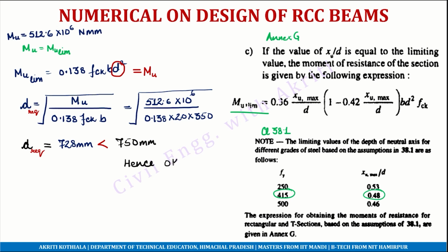Now this is important because earlier when our section failed, rather than taking the value of 704 exactly, we increased the value by 50 mm approximately so that we could satisfy this check. This is the reason, rather than taking 700 as the new value, I assumed the value to be equal to 750 mm and the overall depth to be equal to 800 mm. You can assume a higher value also if you want to avoid failure at this stage. However, it becomes more economical if we keep this additional value low, not very high.